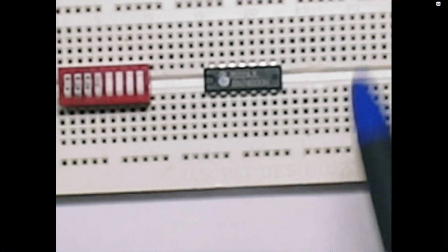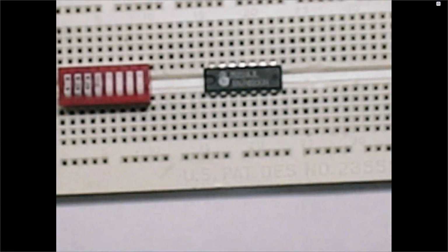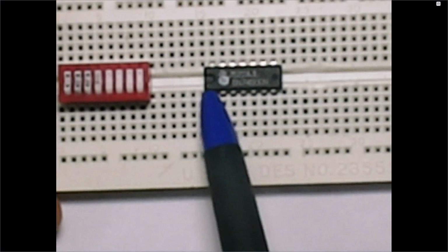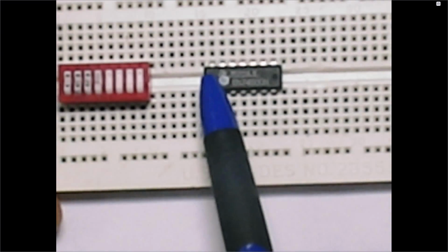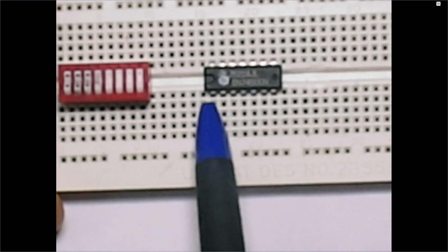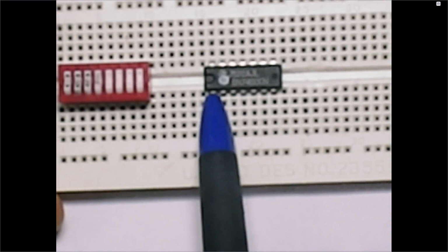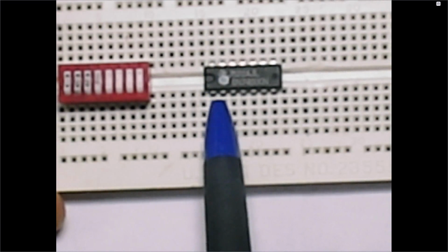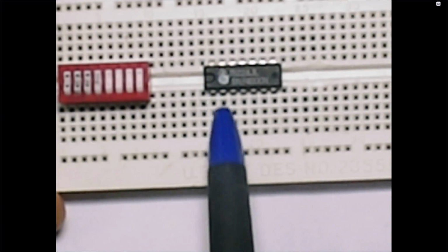Now, how do you start reading the pins? Because you have 14 pins, right? The point is, which pin is number 1? How do you know it? These pins are numbered. They have specific numbers, and the number is extremely important, okay? Remember I said that you keep the card on this side, right? That means this pin will be pin number 1. And you will start reading any IC like that. If you keep the card on your left, this pin will be number 1.